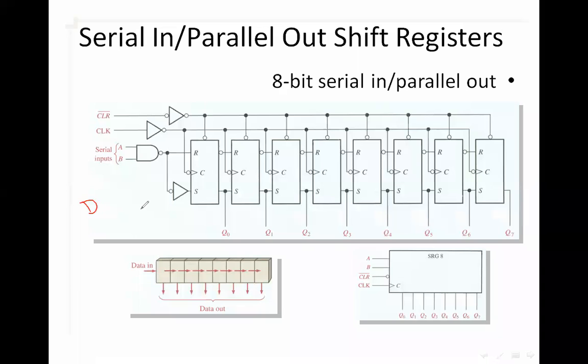Remember I have given a lecture about the conversion of flip flops, and in that I have listed out the equations. There you'll be able to see that when we flip S and R, then it is as good as a D flip flop. So this is the true value of the flip flop, and this is the complemented value of the flip flop. So it is as good as Q and Q bar.